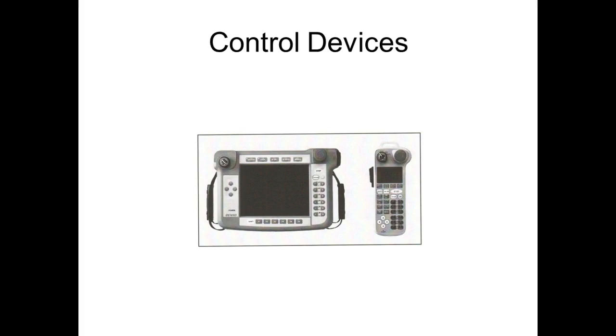So we'll show y'all that too. We've got some videos of a continuous path robot. The little Lego robot that we have can be either point to point or continuous path. We'll take the little car and roll it around on the floor, then come back and put it back over here and tell it to run the program, and it'll do that. But it takes a lot of memory to do that.